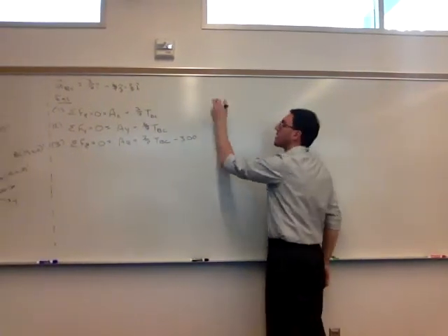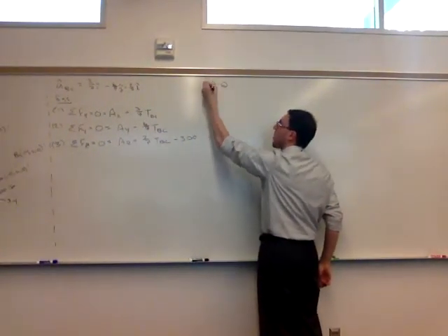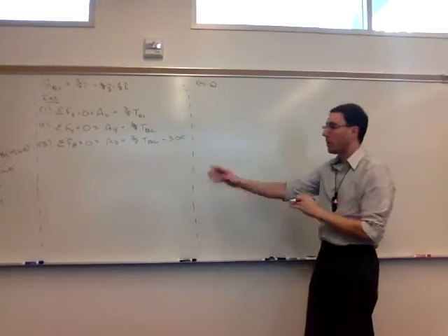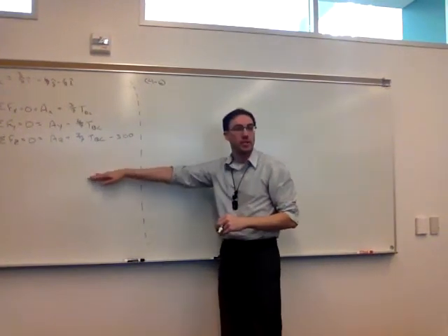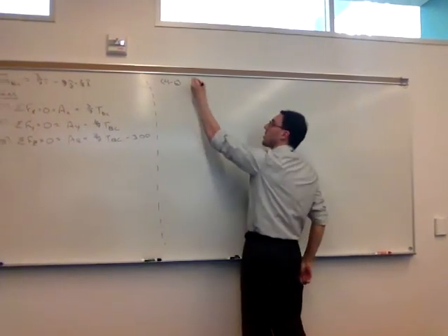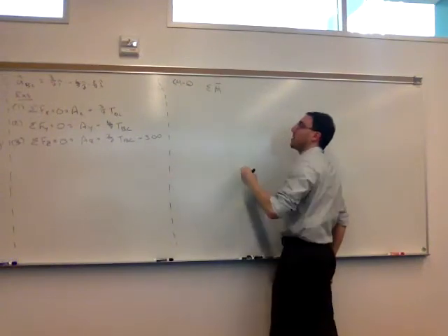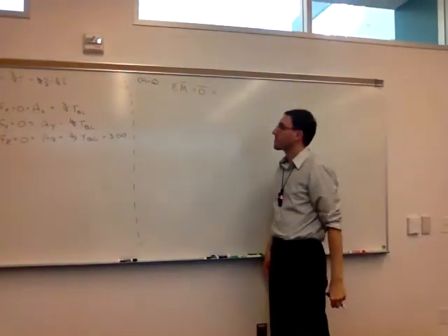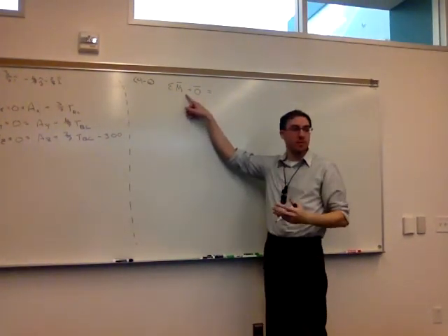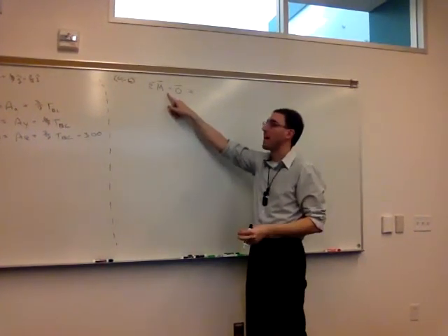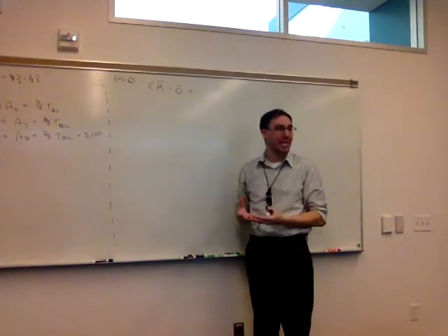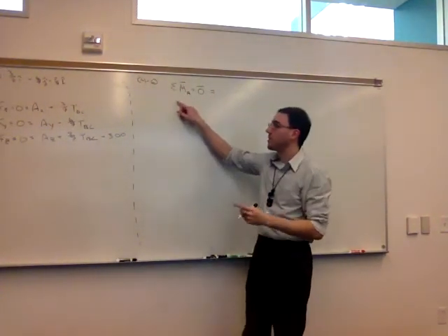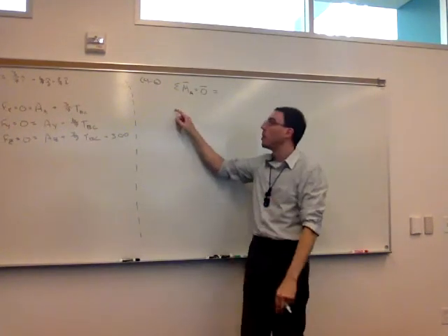So it's a rigid body, so we're going to get 3 more equations by taking the sum of moments around a point of our choosing. So we'll come back and add the rest of the scalar equations here. So this is where we're going to get 3 equations. We're going to take the moment, which is a vector, around some point, and it's going to be equal to the 0 vector. So again, the point we choose numerically does not matter for our answer, but by hand, A is going to be the easiest point to take the moment about, because we'll have 3 unknowns acting there, so none of the forces Ax, Ay, Az will be in this equation.